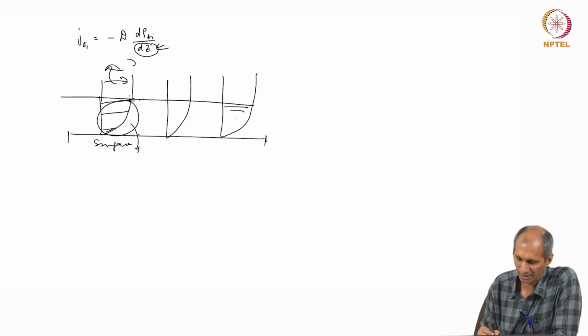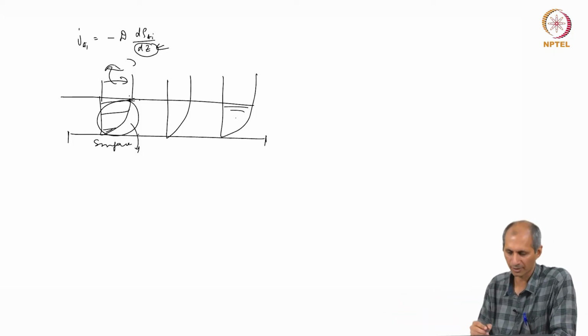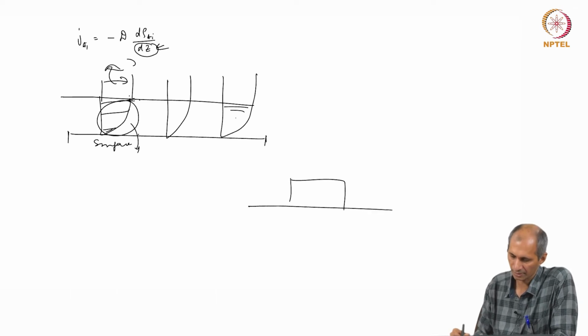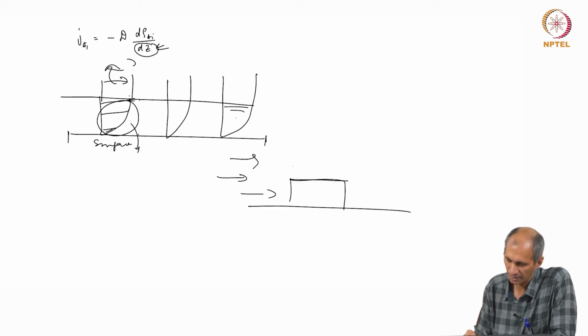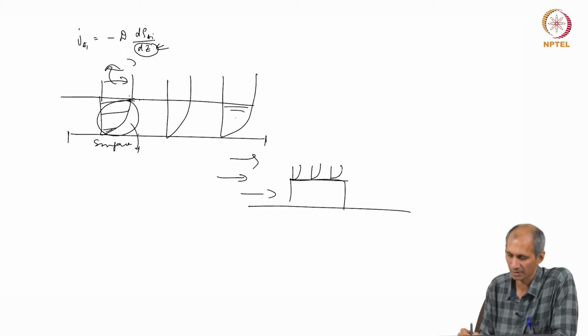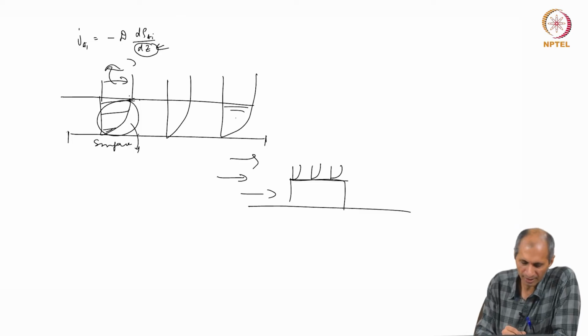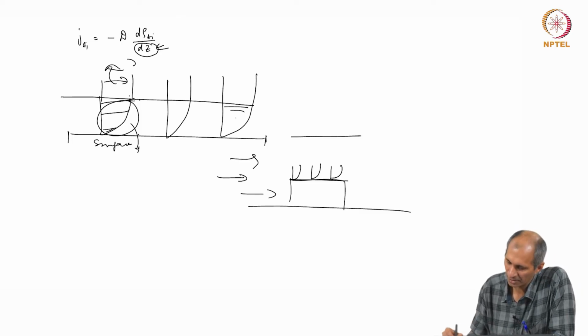The velocity is whatever the approach velocity is. What I mean by approach velocity is, let us take this bench for example. There is a bench and there is air flowing, all at uniform velocity. The moment it hits this bench, the friction of the surface comes into play, and therefore the boundary layer will start forming here, and the velocity profile will start developing. Initially it will look like this, with very little friction happening, then as we go the effect of friction is higher.